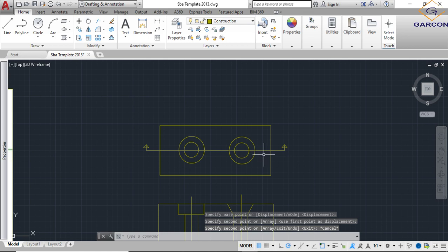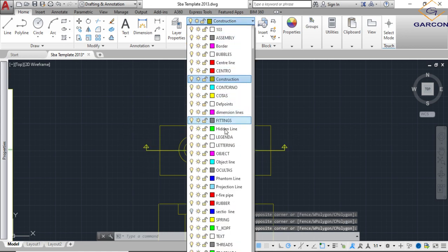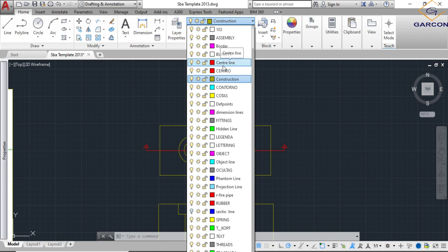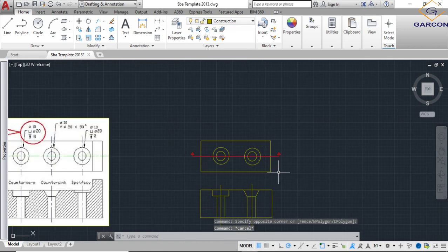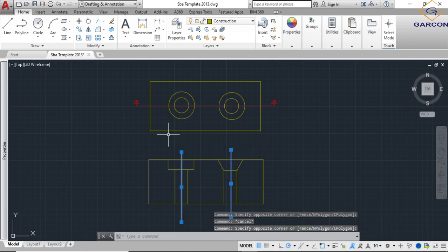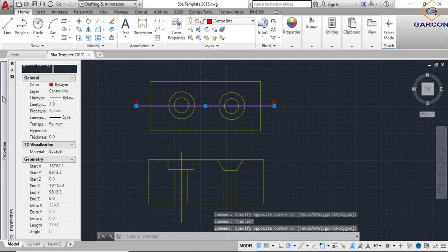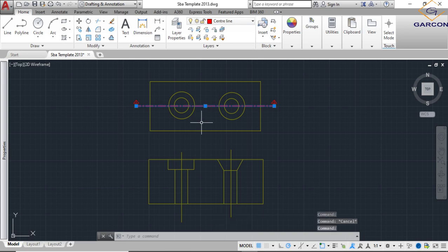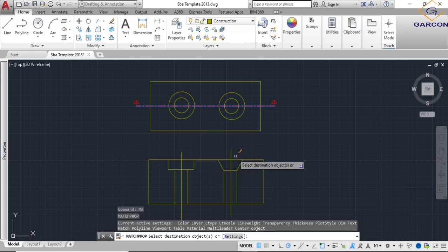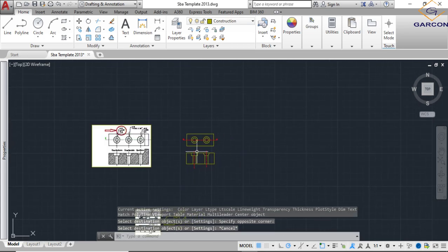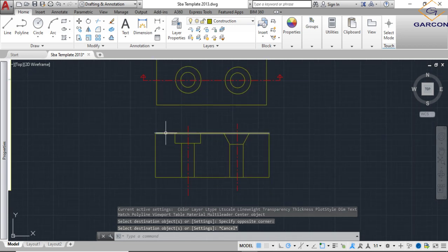So this will be a section line, so I can change it to section line, thin plane. I'll just use center line for now. Boom. This is our center line, so change the line type scale to 15. Looks more like a center line. Then match properties, change these two, good. And then this is countersink, counterbore.